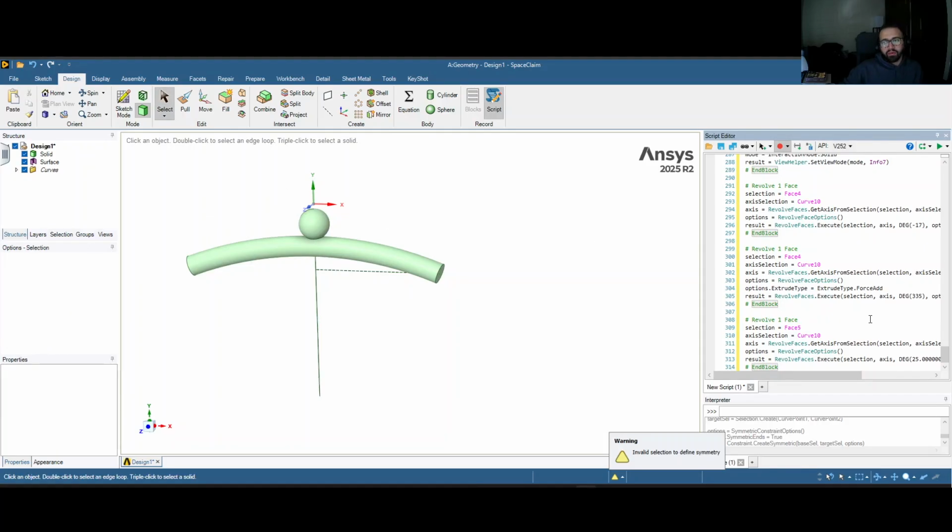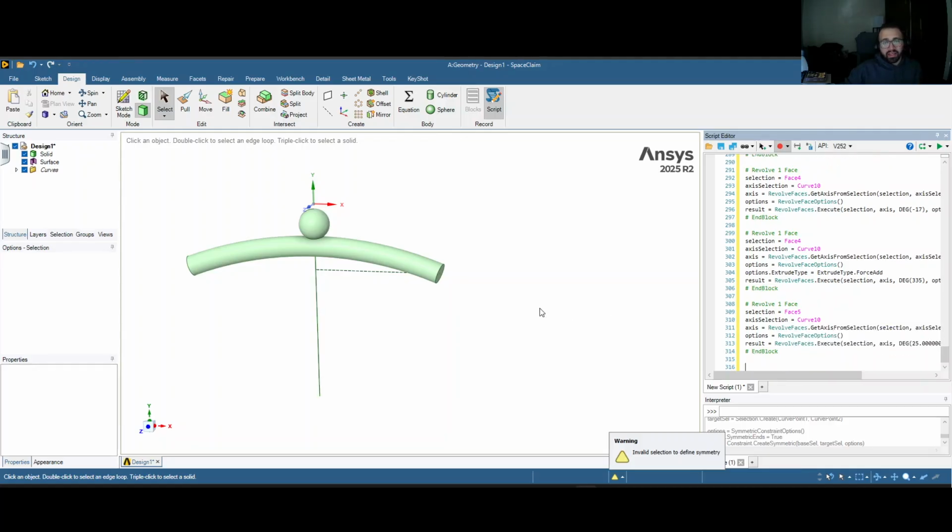Now, a few pieces of advice here. Every selection or every move we are doing here is being recorded. So if you did a move and it was recorded here, make sure to remove it, because doing a move and then trying to reproduce the geometry mostly will result in a fail. The last two steps are creating named selections for inlet and outlets and whatever selections you need to name. The second thing is saving your file.